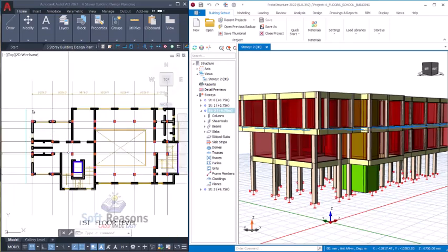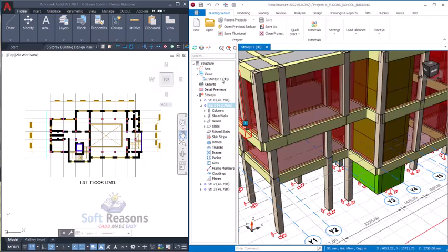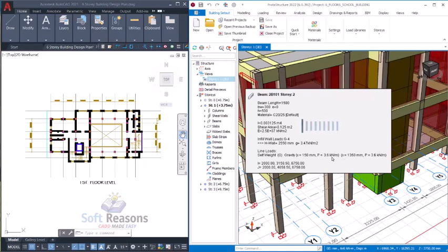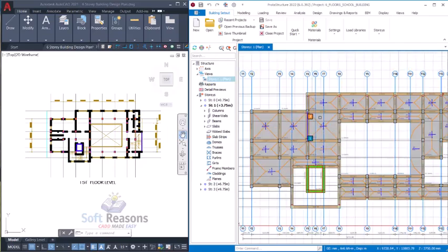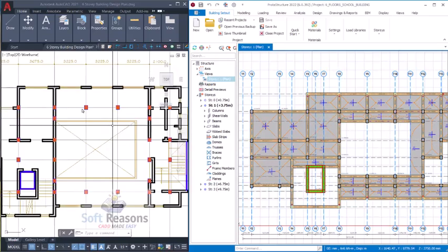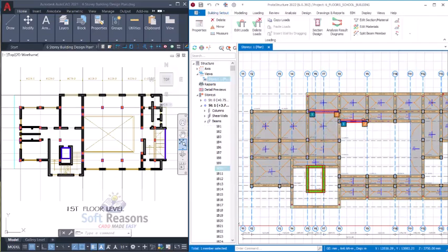You can see the architectural plan first floor right here. Okay, we will navigate to first floor by double clicking on this first floor to move the green lines right there. You can see, and then we get back to the plan view of that floor. Here we go. On this plan view, you can see all of these beams are being loaded successfully. But if you check very well on the floor, you notice that this line has no beam. Okay, also this line has no beam. So we have to get rid of that by deleting the wall load that is on that beam successfully.